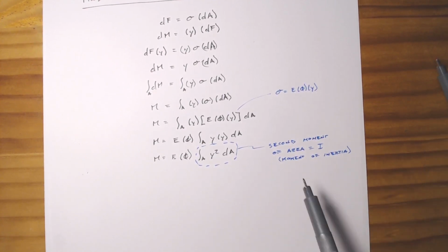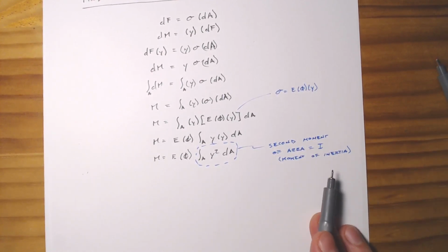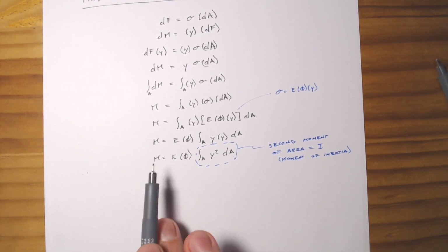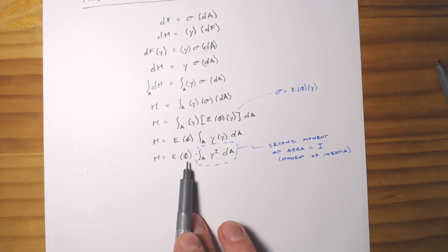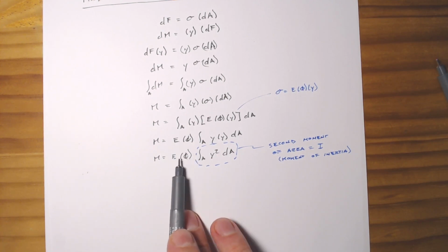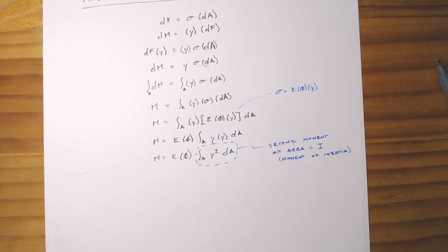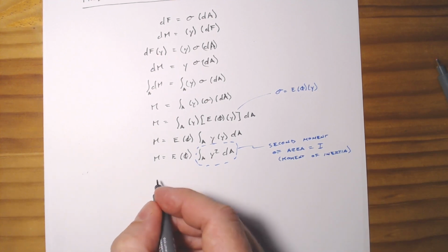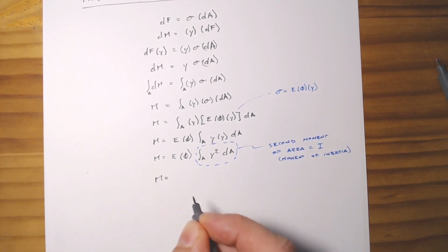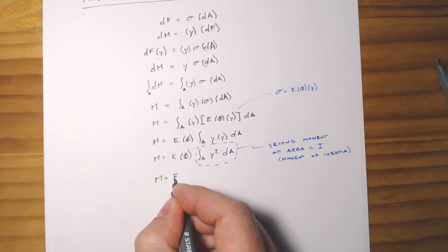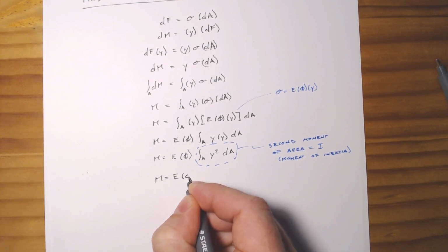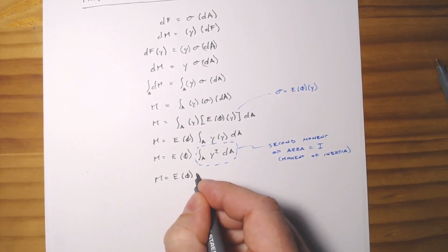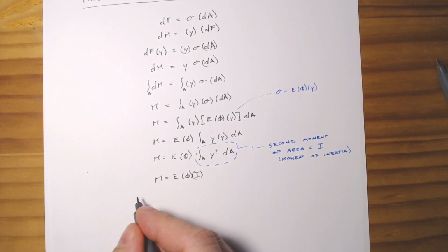So we know how to calculate this. This is just a constant based upon the cross-section, which now all of a sudden means that we have some relationship between our moment, our stress, and our moment of inertia. So M equals Young's modulus times curvature times I.